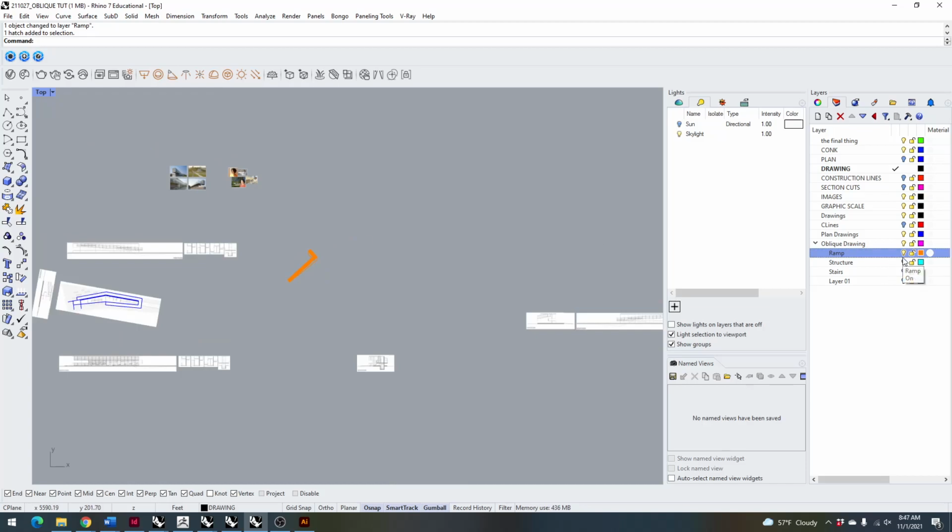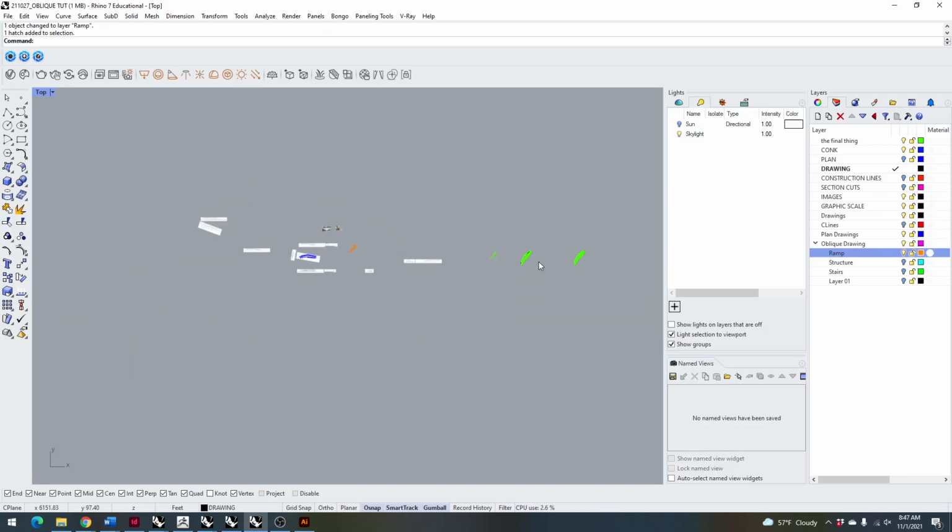The last thing I'm going to show you guys how to do really quickly is to plot your drawing. So once your drawing's done, I'm going to move over to this drawing that is just about finished. Once your drawing's done, we're going to need to plot them in a relative scale because we've drawn them such that their dimensions are the same as the dimensions of the pavilion in real life. So we need to plot them to fit on an 11 by 17 drawing.